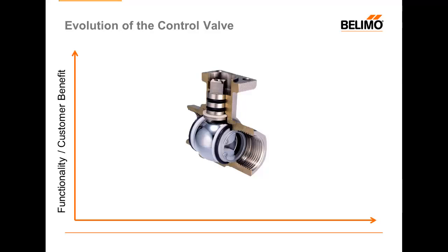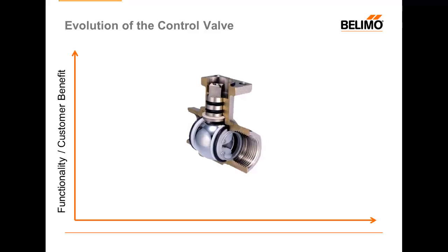The problem with these types of valves is that while the valve may be open the same amount, we don't necessarily get the same amount of flow through that orifice. So if we think about a valve that's halfway open, receiving maybe only a 2 or 3 pound pressure drop, we're going to get a certain amount of flow. But that same valve, in the same half open position that was seeing 8 or 10 pounds of pressure drop, would obviously see a significantly higher amount of water. This is what makes a valve pressure dependent. The pressure causes variations in the actual flow value traveling through the valve and thus through the coil.